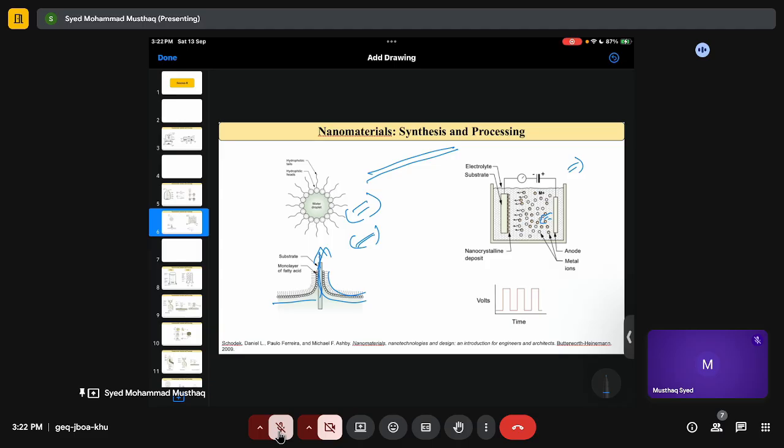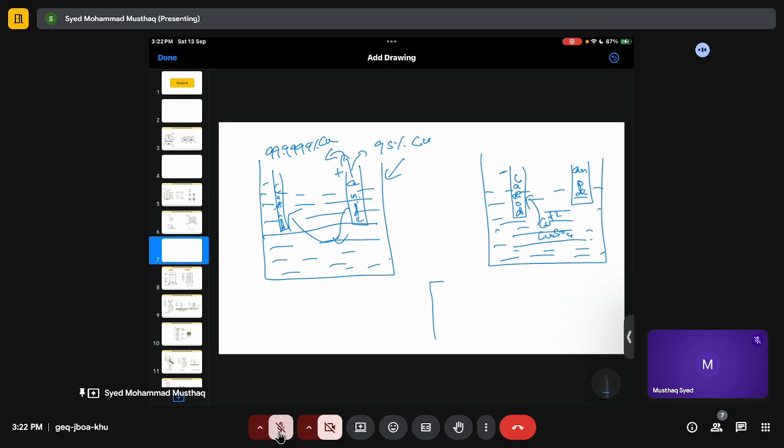Now once you try to do the deposition, what happens is, once we start the deposition, at first it will form in some places, and in some places it may not. Since we are continuously supplying electricity, instead of forming elsewhere, this guy grows, right? So you will have this columnar type structure.